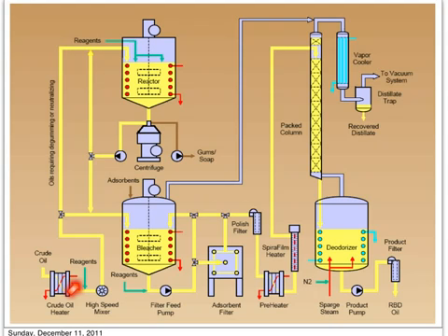phosphatides. The gums or the phosphatides will be removed at this stage in the degumming process. Usually a high-speed mixer is required here to mix the oil and the reagents intimately and uniformly. Then the oil will go through the next step.